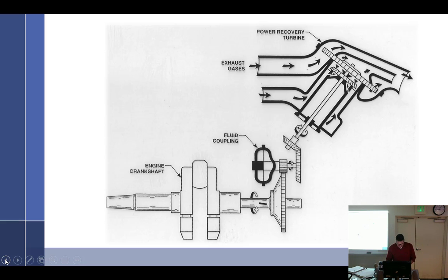Maintenance. Use mouse milk on the wastegate to dissolve the coke. Do not adjust controllers without exact instructions. Keep the induction clamps tight. Look for leaks. Check the fins on the intercooler. Check rotables for damage. Talked about the V-band clamps.